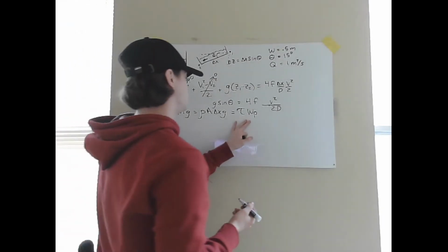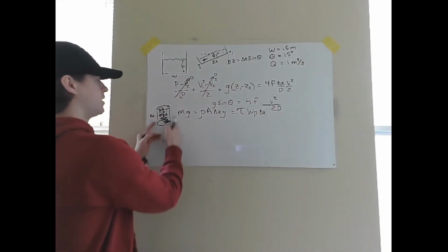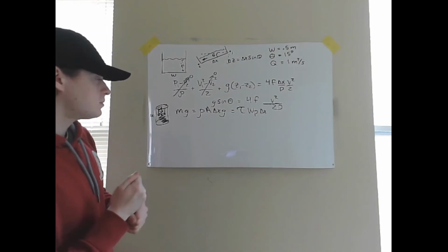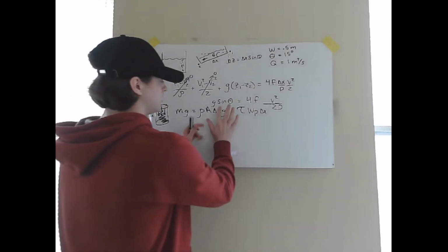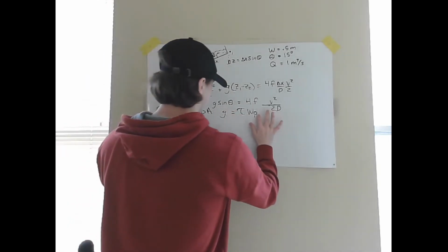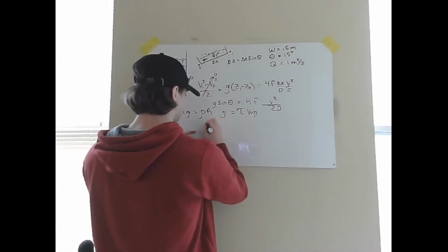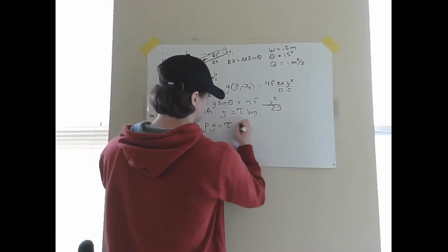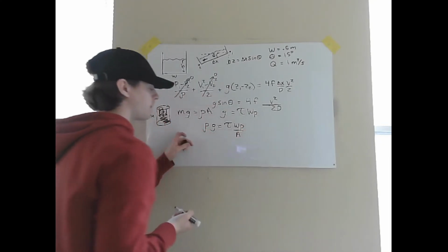And this will be multiplied by the length of our pipe. And so this gives us the total area that is touching the water. And so from here, we can go ahead and simplify this equation a little bit. So the delta x's cancel on both sides. And I can go ahead and move this area to the right side of the equation. So we'll have rho times g equals tau times the wetted perimeter over the area.